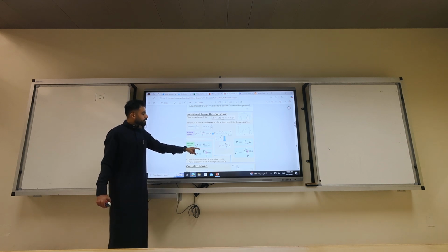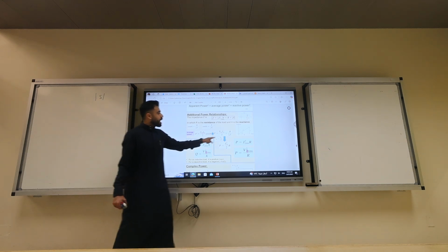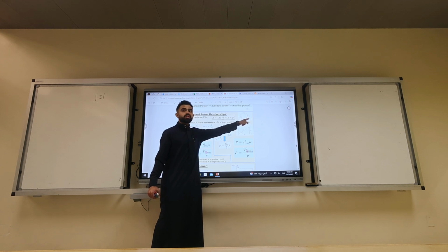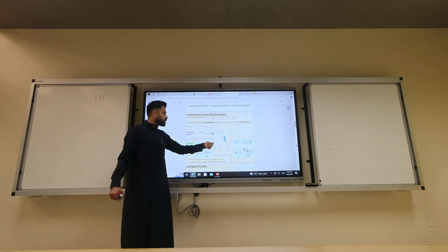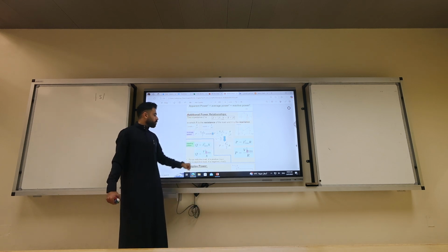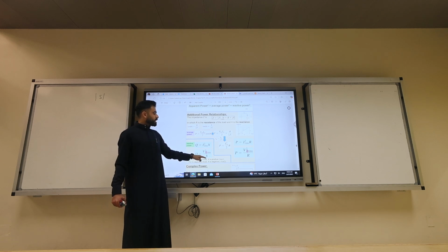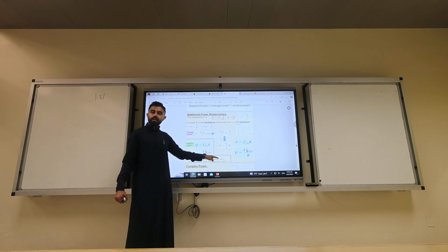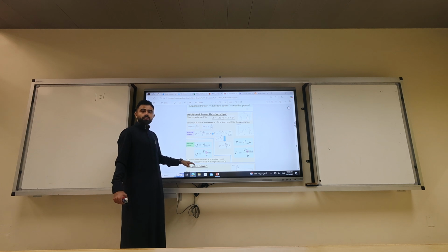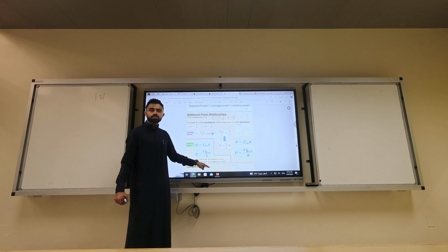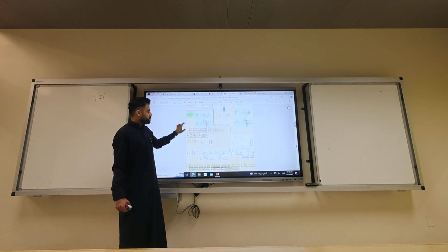For reactive power, you replace R with what? Just X, without the j. We do not put the j in the Q formulas. For an inductive load, X is positive, plus omega L. For a capacitive load, Brahim, X is what? Negative, which is minus 1 over omega C.